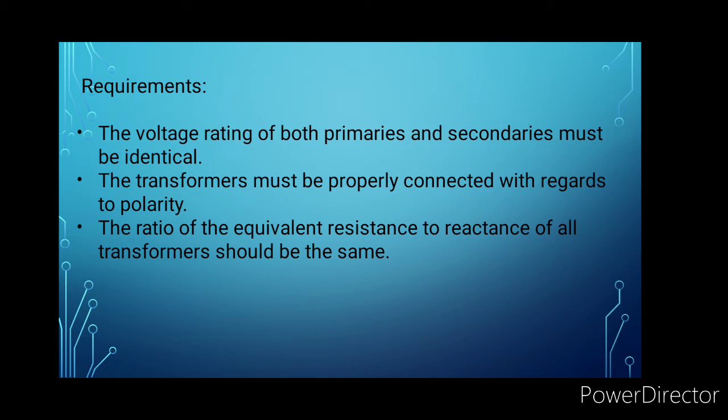If there's a difference in phase angle, it also results in one transformer working with a high power factor and the other one with a lower power factor. What will be the effect of the power factor? It may affect our apparent power.